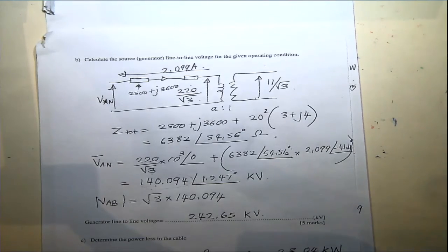I want to check, how did you find this angle for the current in the plant? Is the case going to be similar to that? Yeah, fairly similar, different numbers, same questions. Here it says 0.75 power factor, so you take inverse cos. Most of the time, I do inverse cos.